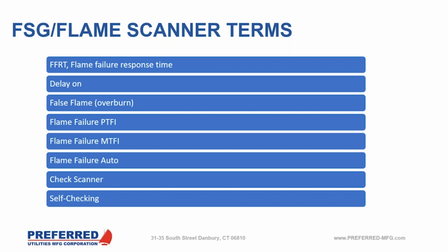A lot of times when I've actually been in the field and seen this particular flame failure, it's been just a case of adjusting the pilot fuel regulator to get a little bit stronger signal there. A lot of times that's all that's necessary to fix that particular problem.